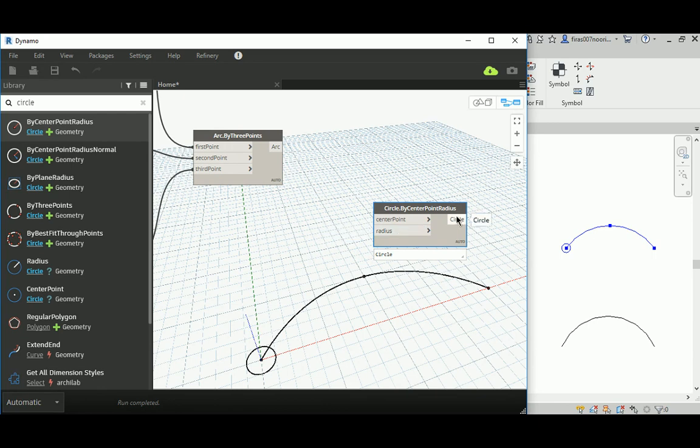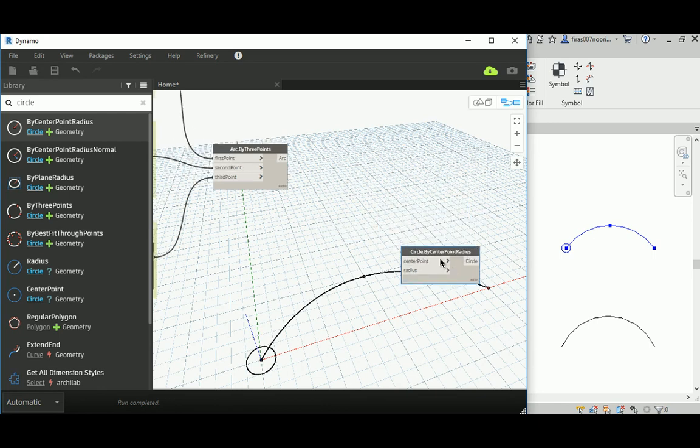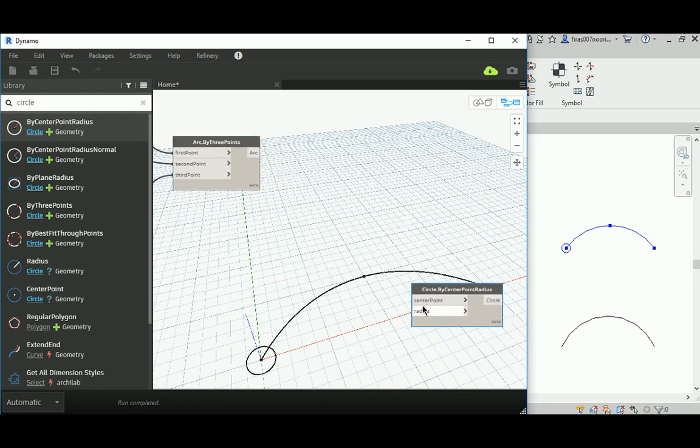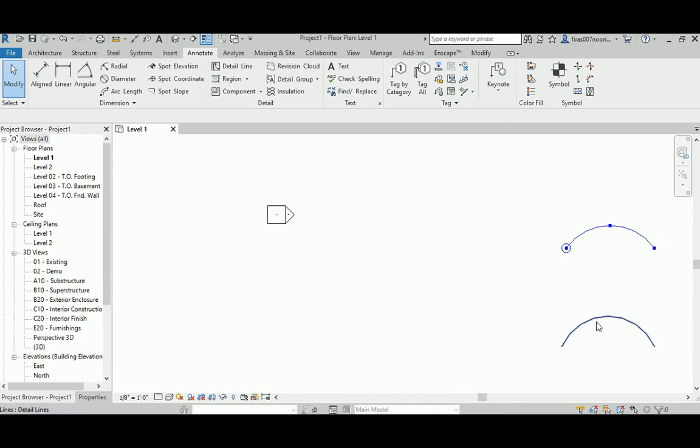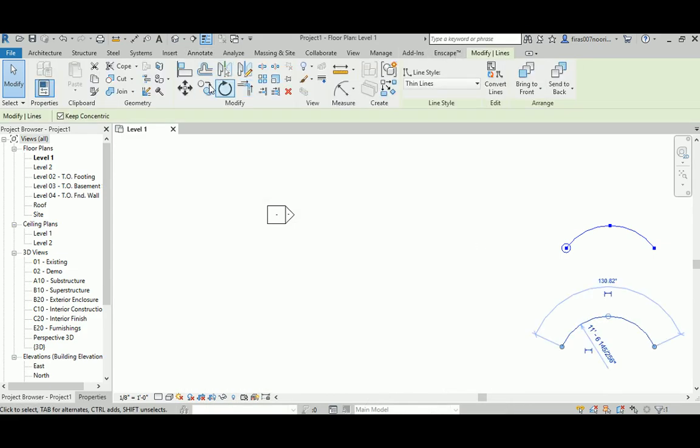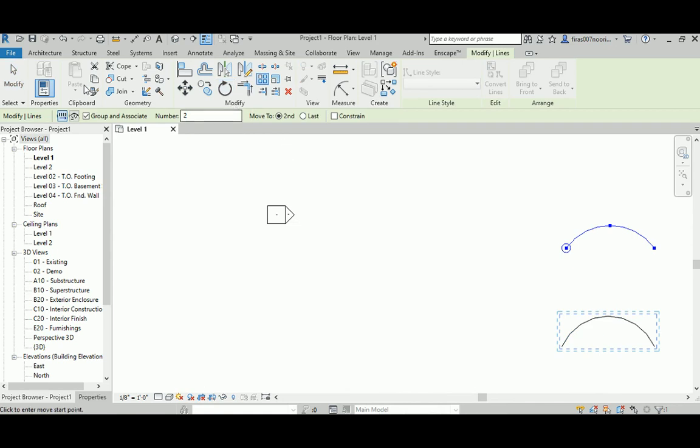So far so good. Now how about if I want to make this circle go all the way along that curve? If you want to do that in Revit, your brain goes a little bit slow, and you don't know what tool you need, because if you select that guy and go to Modify, you have Array. I don't know why Autodesk has still not made the array by line or array by path.